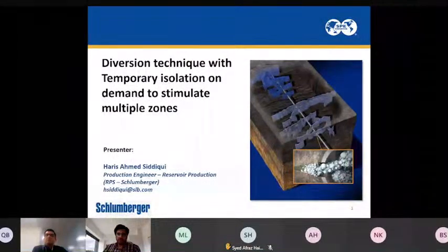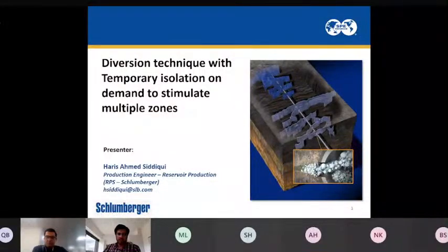So I cannot quantify the time here. It depends on the technique of hydraulic fracturing and the completion being used. The flowback will be the same, and it varies with the reservoir formation as well. For a tight formation, flowbacks will be longer. For a conventional formation, it will take less time.